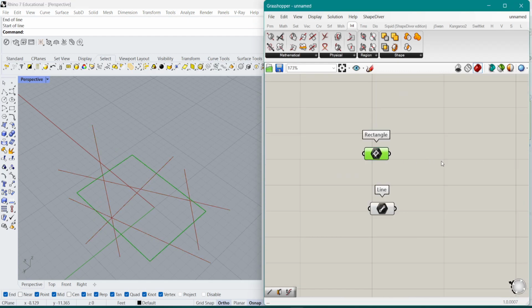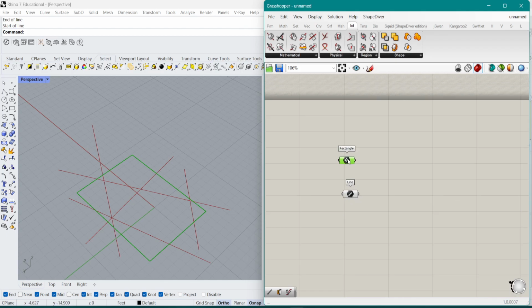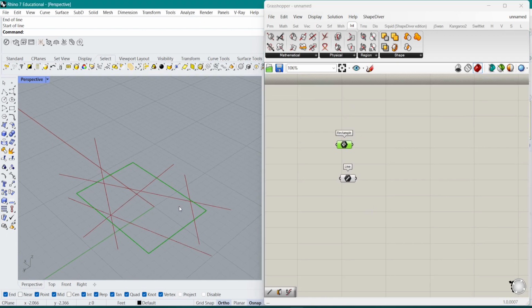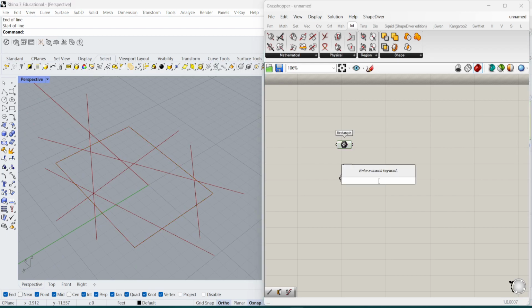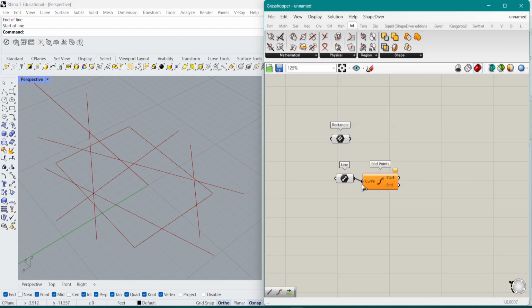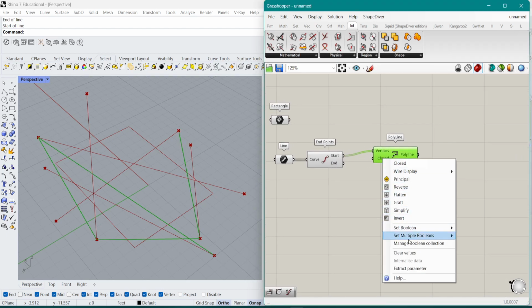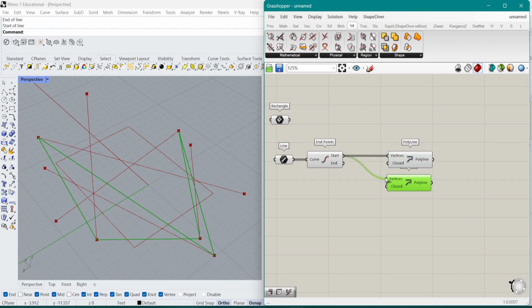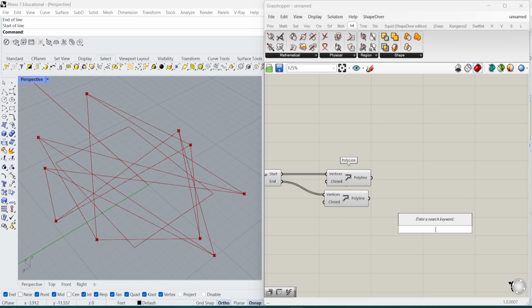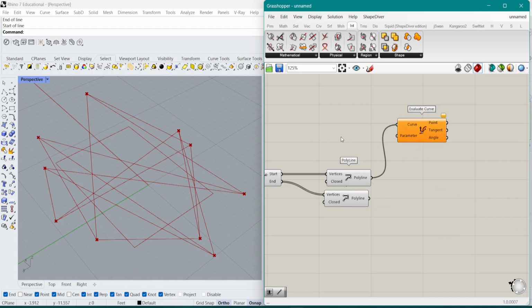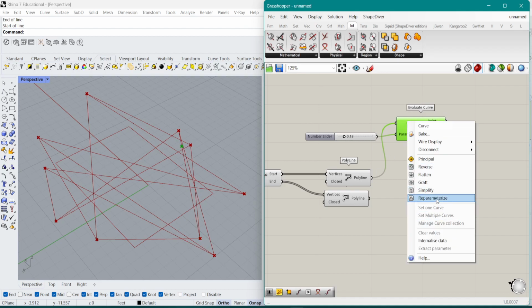Now that we have the lines created, we basically want to create this kind of revolving mechanic that we saw before, so that we can go around the place and have different scenarios all the time. I did it in the following way; obviously there are different ways to do it. Here I just create the end point like this, create a polyline, and then close it by setting this to true, and then do the same with the endpoints. Then I create an evaluate curve command, so I can see how this point would look. And here I need to reparameterize the curve.